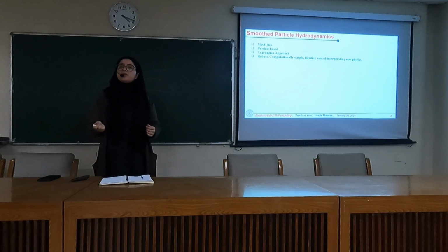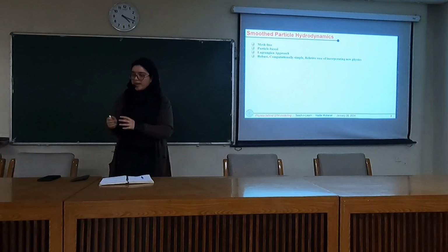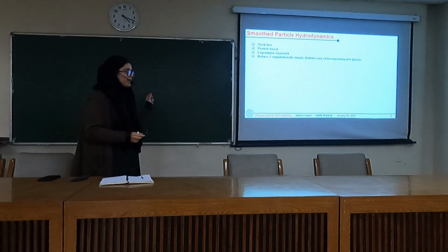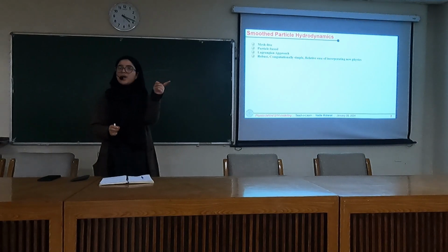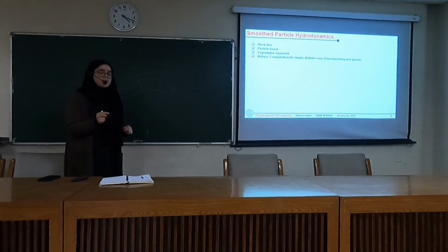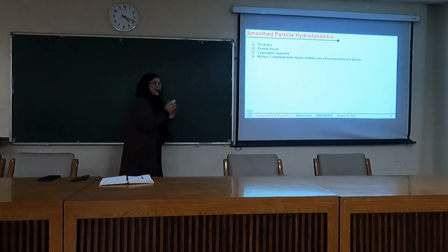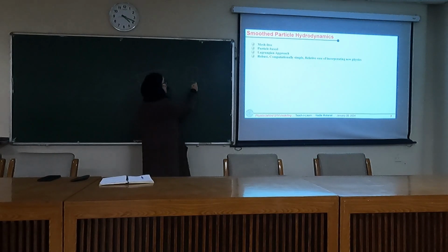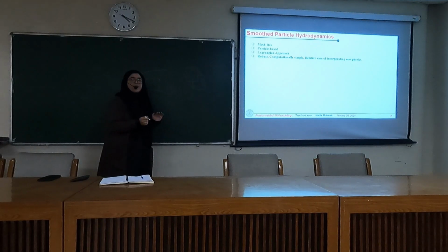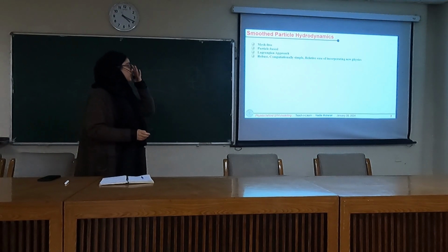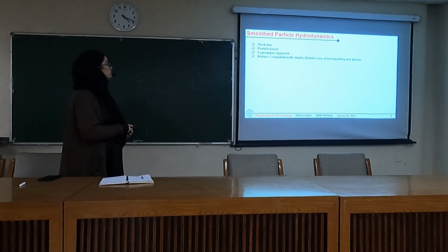It's like, for instance, a woman carrying her dog. She is tracking her movement, her velocity, her position. She can track it at each and every point. So we are following one point as it moves from one point to another in the Lagrangian approach. However, in the Eulerian approach, we have a volume element. At any point of time, we are focused on how much fluid or how much continuum is trapped within this volume element. That's the Eulerian approach. So here in SPH, we are using the Lagrangian approach.